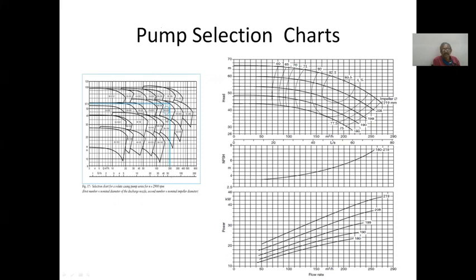So for your discharge and for your needed pressure head, you get a point, and here you find values, and these are all the individual groups of pumps. Somewhere 80 to 200, like that, it is given. For 80 to 200, that can be a model or an HP or anything. It's a code. For 80 to 200, you will have separate detailed characteristics, something like this.